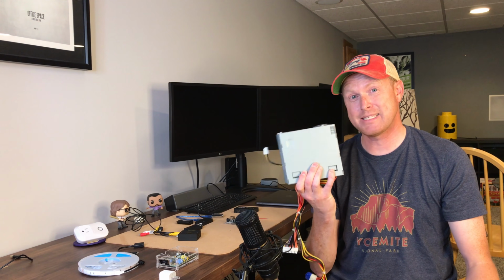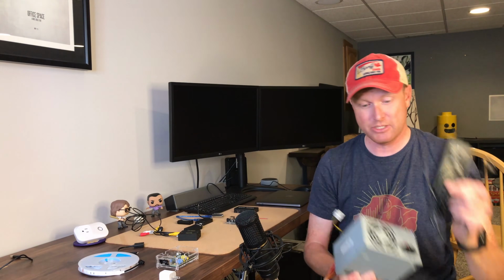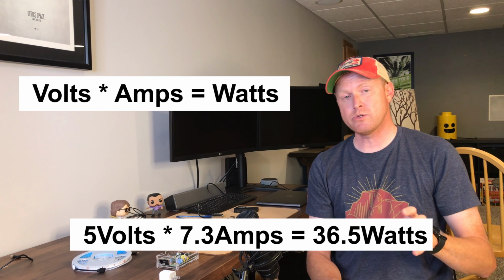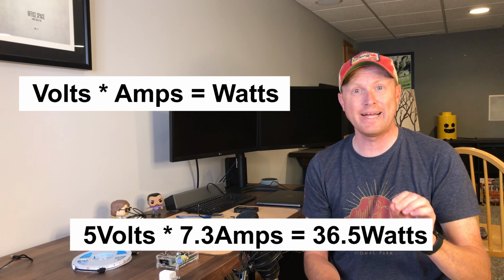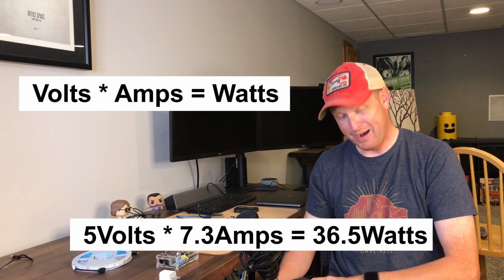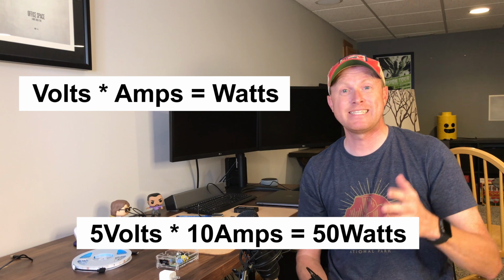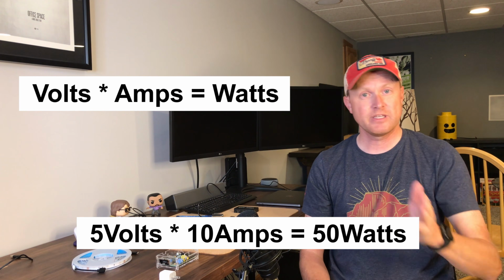I'm going to show you how I set mine up in a second, but let's talk about this. The LEDs that I have around my TV, I have 110 LEDs around the border, and that uses about 7.5 amps of power at 5 volts. So that equals about 35 to 36 watts of power. We need a power supply that has a wattage higher than that 36 watts. So when you're looking for a power supply at 5 volts, get one that's about 10 amps. So 5 volts at 10 amps.